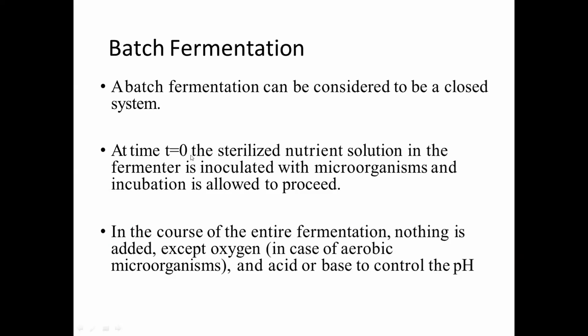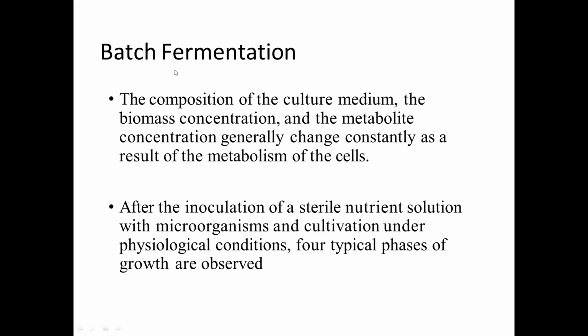At time t equal to 0, the sterilized nutrient solution in the fermenter is inoculated with the organism and incubation is allowed to proceed. In the course of the entire fermentation, nothing is added except oxygen and acid or base to control the pH. So, except oxygen and these acid or base buffers, you're not going to add anything during the fermentation. This is the batch reaction or batch fermentation.